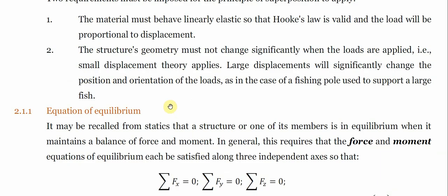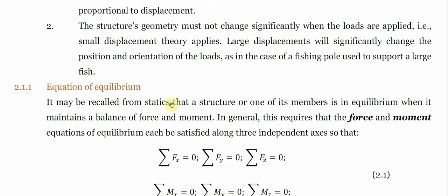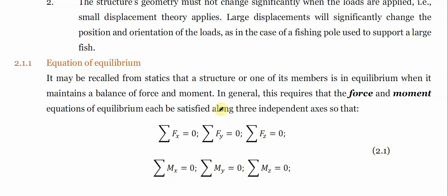Now, as we all know, there's what we call the equations of equilibrium, as we already studied earlier on. There are six equations of equilibrium that must be understood when treating an object: summation of forces along the x-axis must be equal to 0, summation of forces along the y-axis must be equal to 0, summation of forces along the z-axis, that is when we have our x, y, z, our 3D shape, they must sum up to 0 before you can treat such a member.